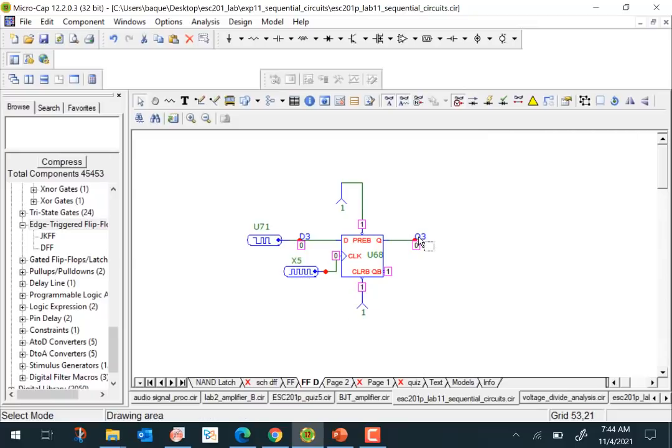Normally, the output responds to the input only when a positive edge comes. Then only will the output change in accordance with the input. We call this a synchronous operation, which synchronizes with the clock. On the other hand, these are asynchronous inputs, and they are used for clearing the flip-flop or setting it to a particular value.